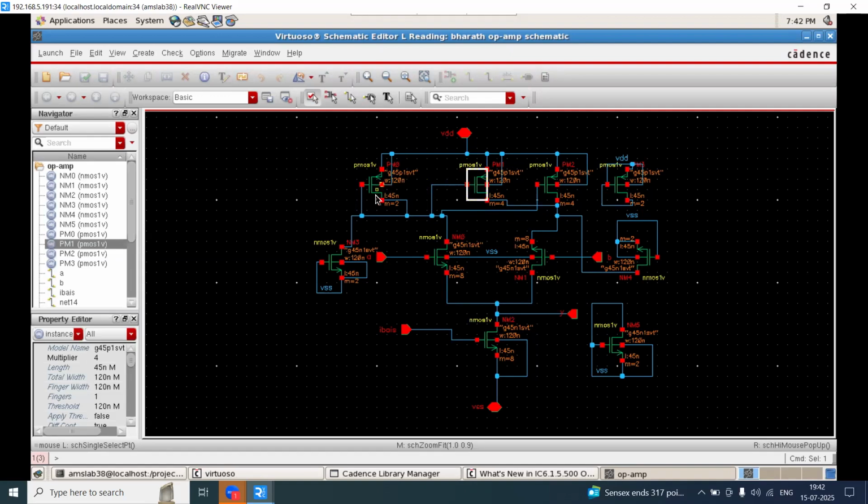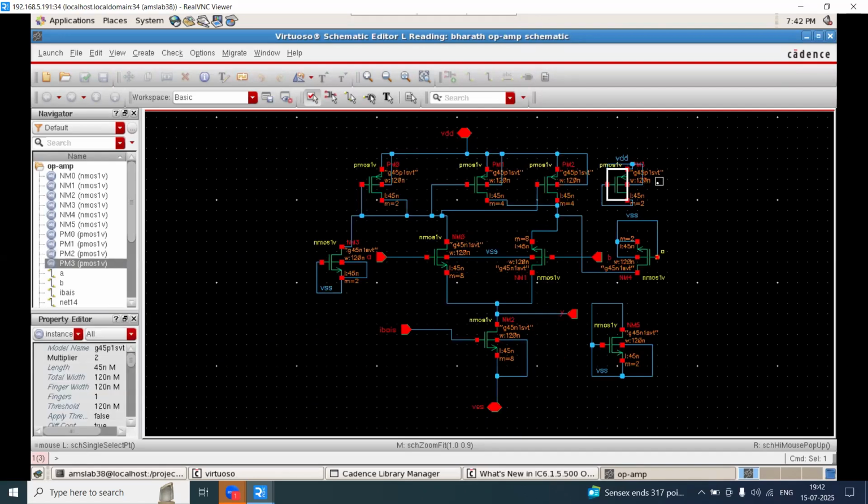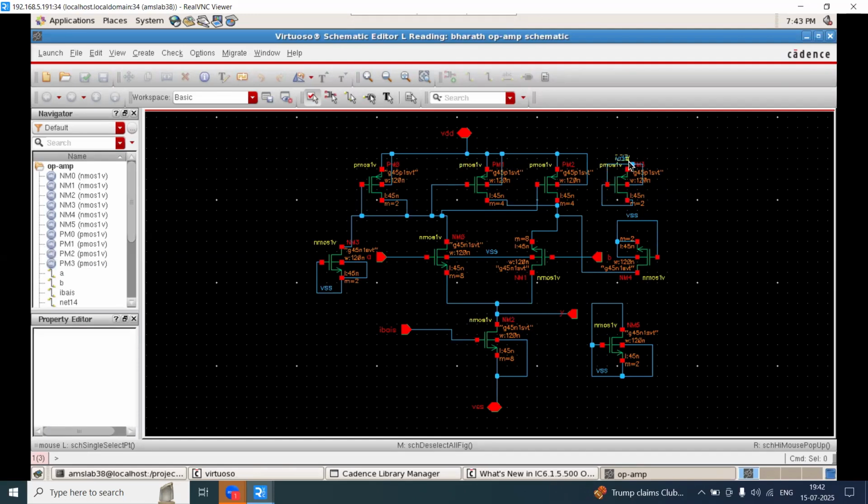We are copying current from this diode connected device to slave device 1, slave device 2, and this is a dummy. Here, the last one, I have taken one dummy. How do you define that this is a dummy? Sir, everything is connected to VDD. Yes, all the nets are connected to the same VDD supply. It is a full dummy.